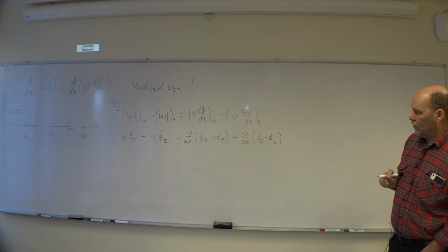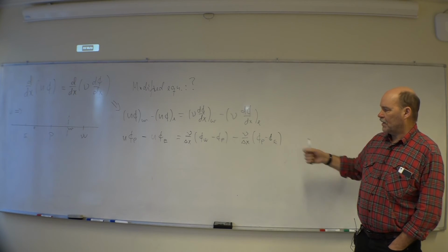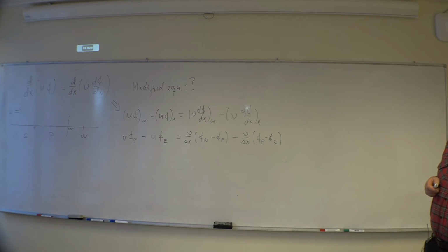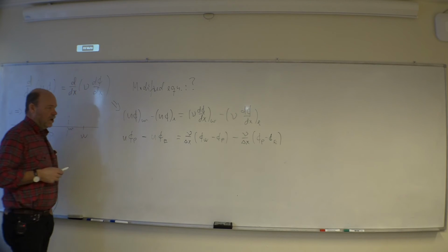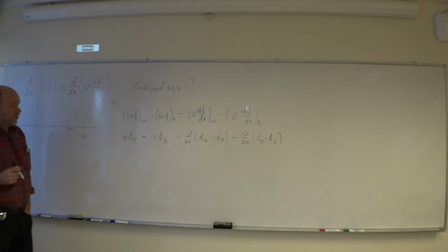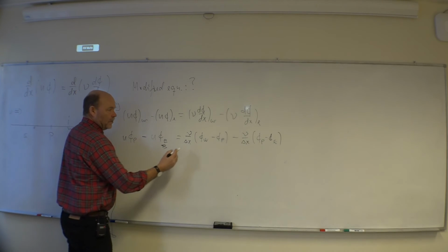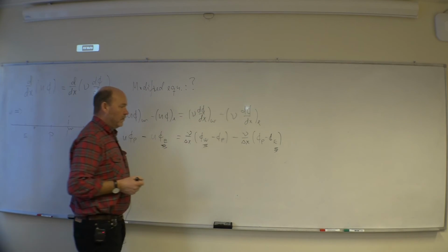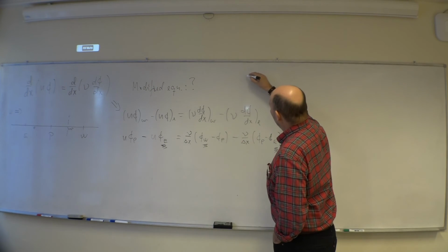Now you see if you take this equation and you divide it by delta x, you will get exactly what we normally get when we are looking into the finite difference world. Never mind that. We are going to need some Taylor expansions for anybody outside the center point. So these three we have to provide with the Taylor series.